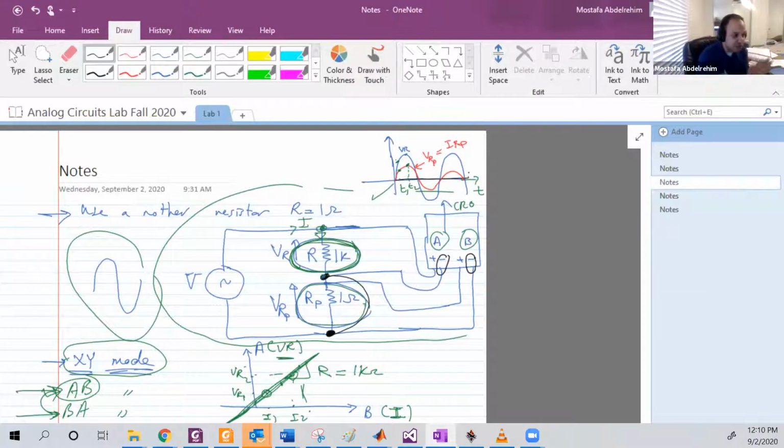By default, the 2 grounds, the 2 negative terminals of the 2 channels, are internally connected to each other. If you get a multimeter and set it to the beeping mode that checks for shorts, and you put the two terminals of the multimeter on these two negative terminals of the oscilloscope, you will hear the beep because there's a short.